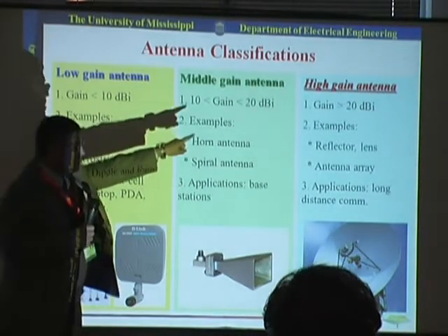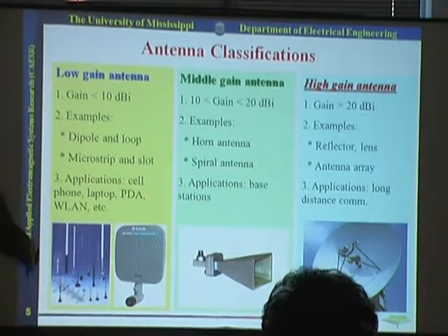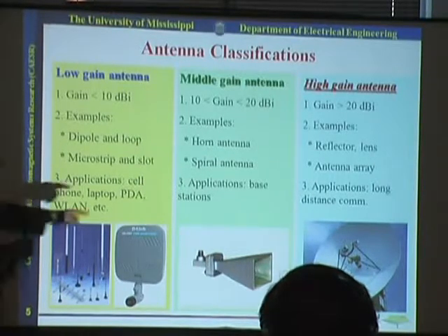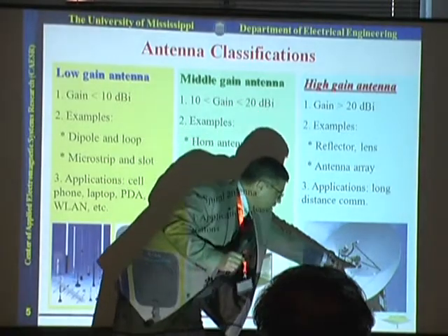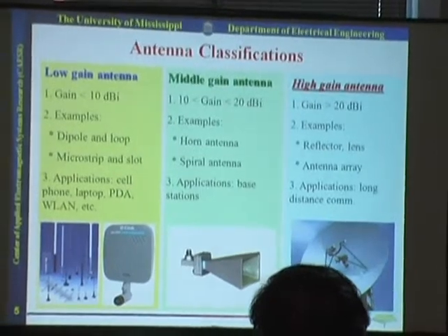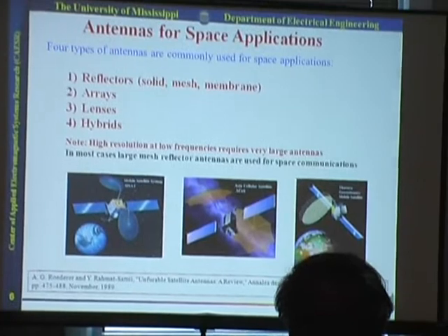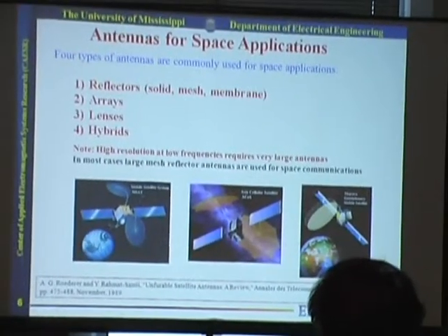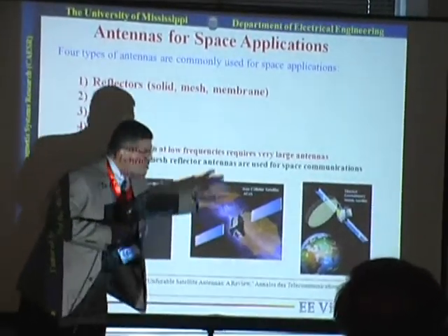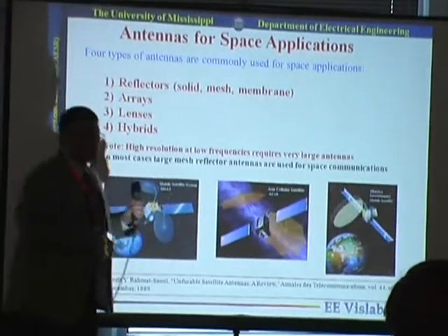We are interested in antennas that have high gain, and most of the time you use a parabolic reflector antenna, a big dish-shaped or pyramid structure with a feed either at the focus, or another sub-reflector with the feed at the center of the reflector itself. It is a very clumsy structure, very efficient in terms of gain, but it's not very practical in many applications. You can see some of those reflector antennas here made out of mesh, made as an umbrella that you can fold when you launch it in space.